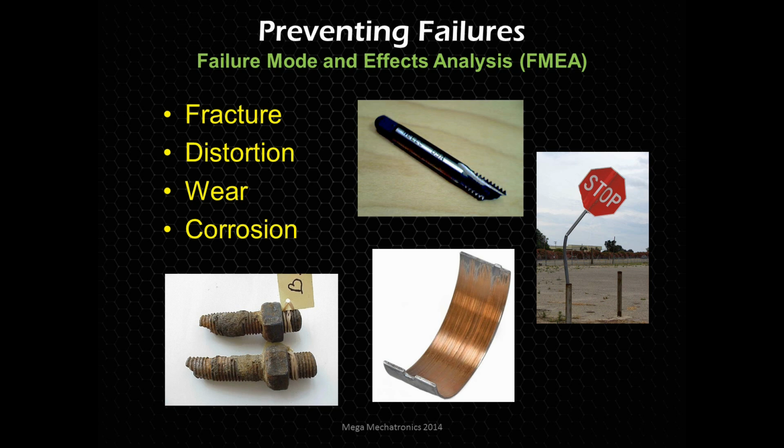So things you could change for distortion failure is to prevent that distortion, prevent something from hitting it, prevent a car from running into it, increase the structural rigidity of that system. Where do you need to improve the lubrication systems? Did you forget to lubricate it? Does it need a different type of material for the parts mating with each other? Does it need more surface area? Things like that.